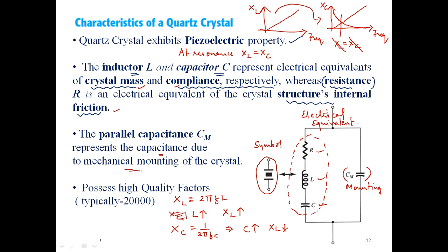Now what remains within R, L and C is that the XL gets cancelled with XC whenever there is resonance, so that it is only the opposition offered by the resistor R that remains during the resonance. I repeat, at resonance XL becomes equal to XC. With respect to their phases, both of them cancel, and it is only the effect of the resistor that remains.